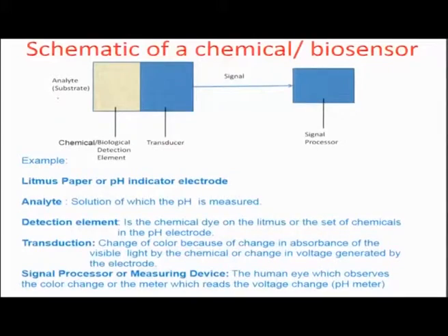We were talking about sensors and the sensorial model of an analyte being investigated through a recognition element, which is generally immobilized on the surface of an otherwise constructed detector. The detector typically does a transduction, in which the chemical signal is converted into another machine-readable signal, which can be electrical or optical. The signals are sent to a signal processor, which interprets them based on the nature of the signal, and that way one can understand the analyte better in terms of its chemical or molecular composition.